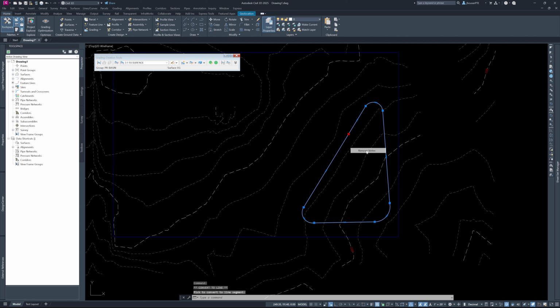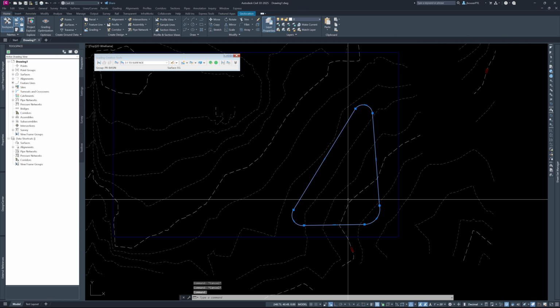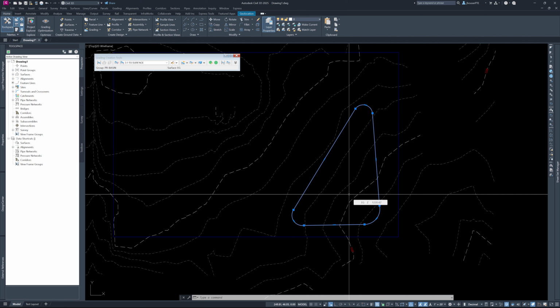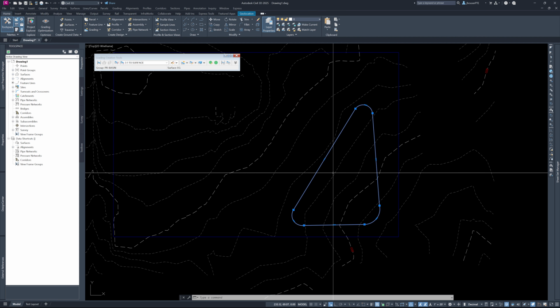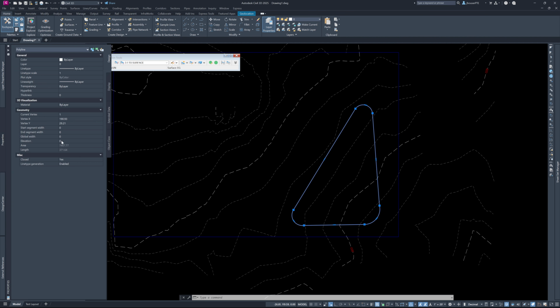It's individual. Now, the next step we want to make sure is, okay, if this is the top of the berm, what elevation should that be set to? Like I said, we're going to probably go about 4 or 5 feet above the lowest outfall. So this is 1218. So let's set this at, I don't know, 1223. So nice and simple, just a regular elevation. Now, I do recommend that you do not put the elevation at an even contour number or elevation number.